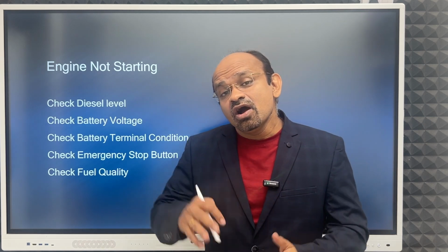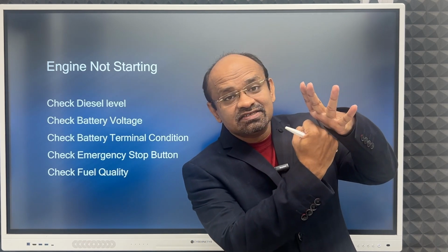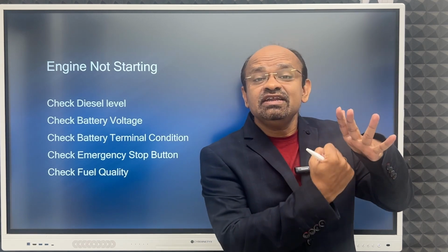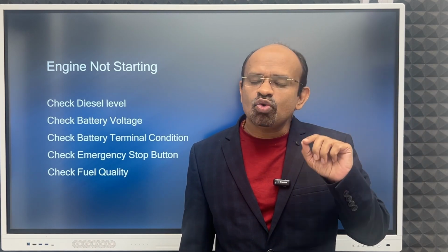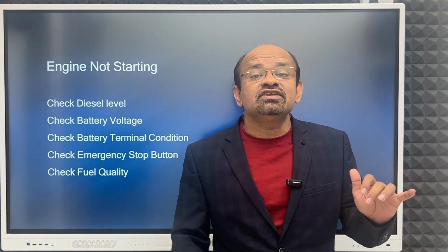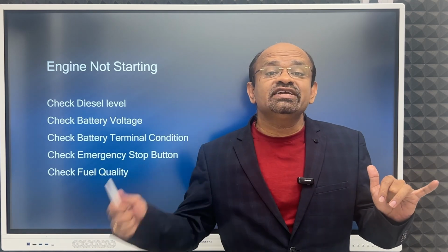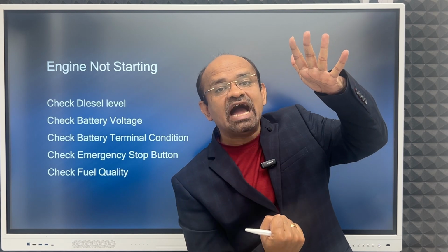See, what is doing this action at the start in the diesel engine? Suction, compression, then power stroke and exhaust, 4 strokes. Who is doing this at the start? During old days, if you see the old black and white videos, the cars were having handles. So they were starting the engine or prime mover by rotating it with the hand. So that movement will happen and it will create the appropriate pressure so that blast will happen.